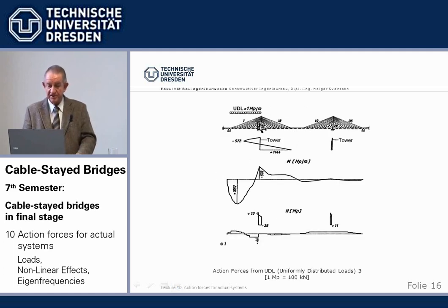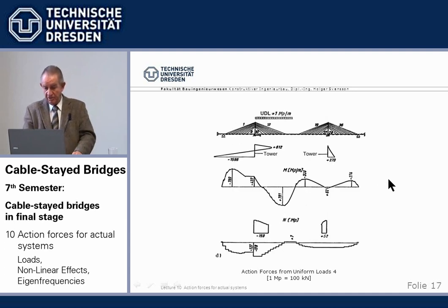If we load the side span, on the other hand, then we have here the big positive moment, sagging of the beam. And there's nothing here, so it's negative here, and then it tapers out. This is something in between.